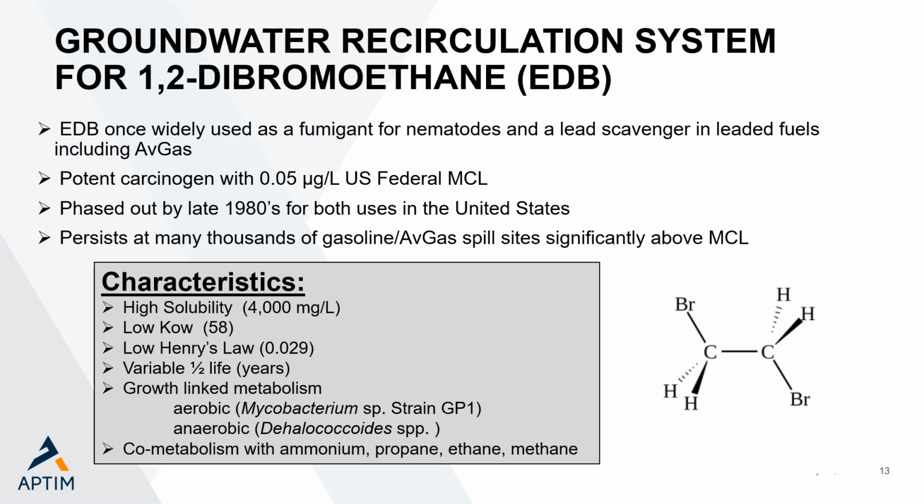Characteristically, it has a very high solubility and a low KOW, the octanol-water partitioning coefficient, and a low Henry's law constant. What that means is it's hard to remove from water. It's hard to strip. It's hard to adsorb to carbon. Microbially, there are some organisms that grow on it, but concentrations are very, very low in groundwater.